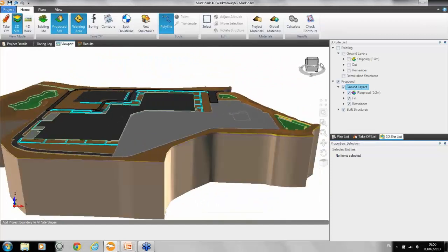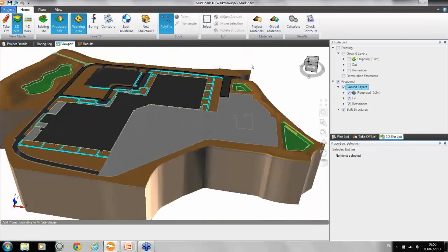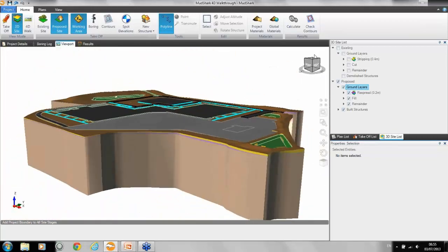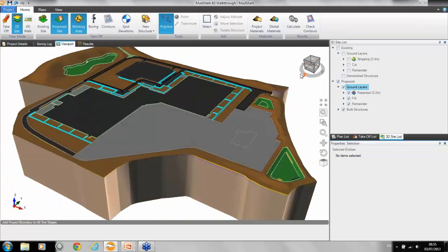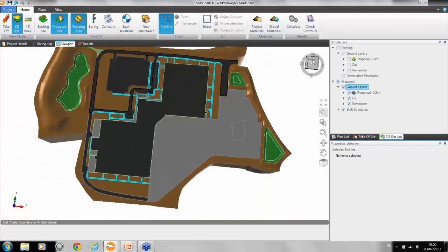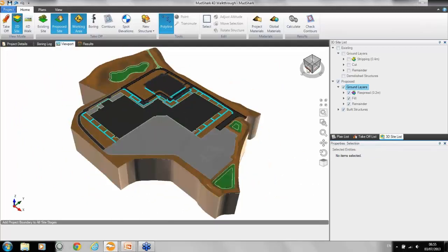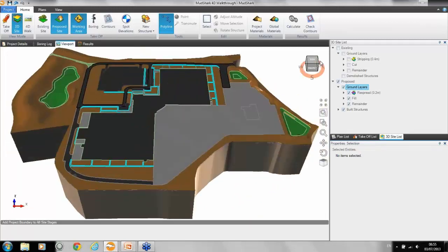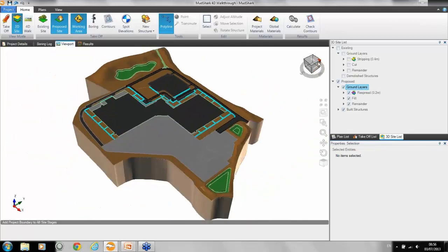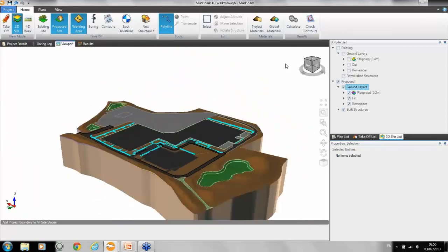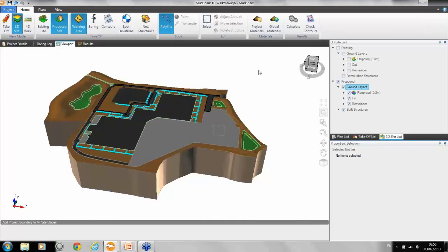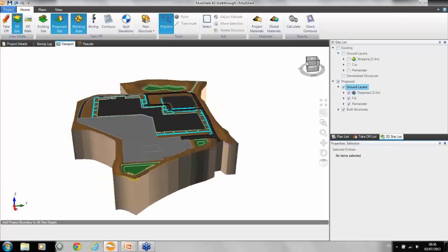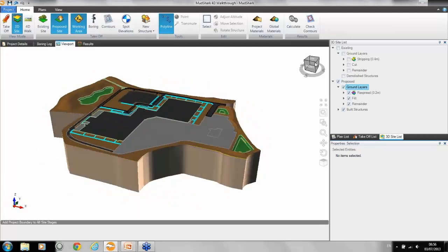Anyone familiar with AutoCAD or similar would be familiar with the cube option and how good it is. It allows you free rotation of your site as you're going along. It also has certain fixed positions, such as the top of the site. You can look at the top right hand corner, the front of the site, whatever you want. They give you quick, single-click snap operations to get a look, so it's an easier way to work from the site. And if you are taking snapshots, you can position your camera at any angle for yourself.